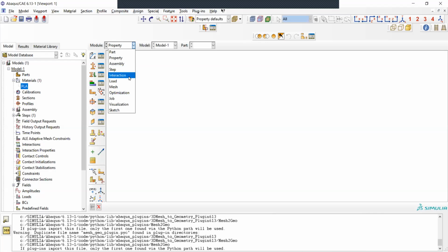When you have several parts, especially in our case, in the case of the table, we need to have an interaction. So you need to define the friction forces, and you need to define the reaction forces. And there's a lot of details there. You have a dynamic friction, you have a static friction, you have a varying logarithmic friction. There's a lot of different models that you could choose from.